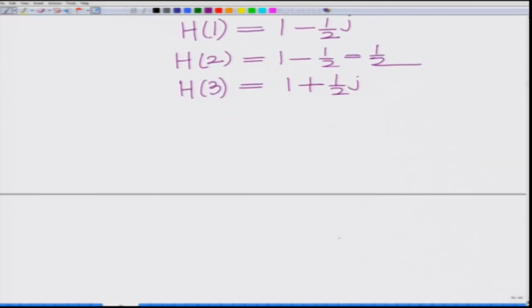And now what we said is basically across the nth FFT channel or across the nth sub channel we have YL equals HL XL plus VL.